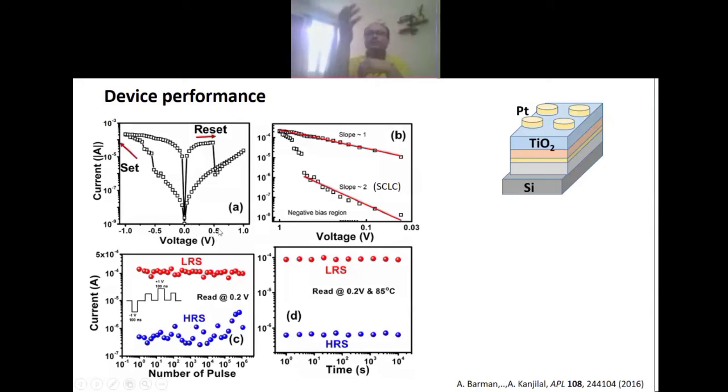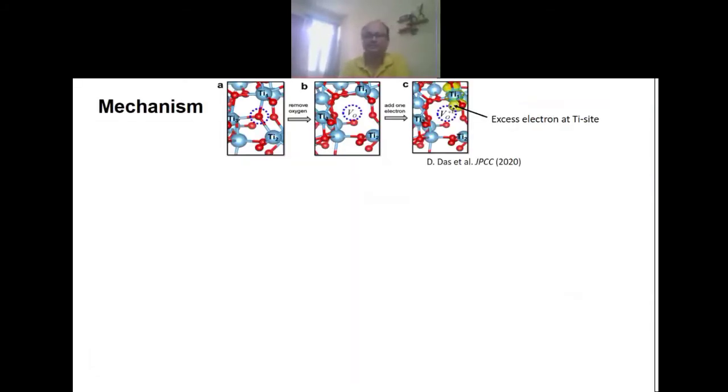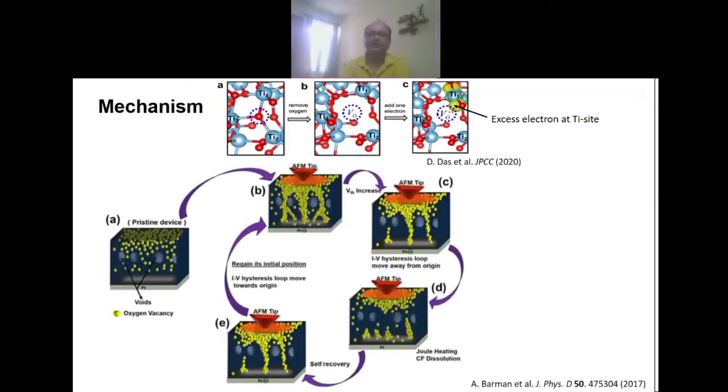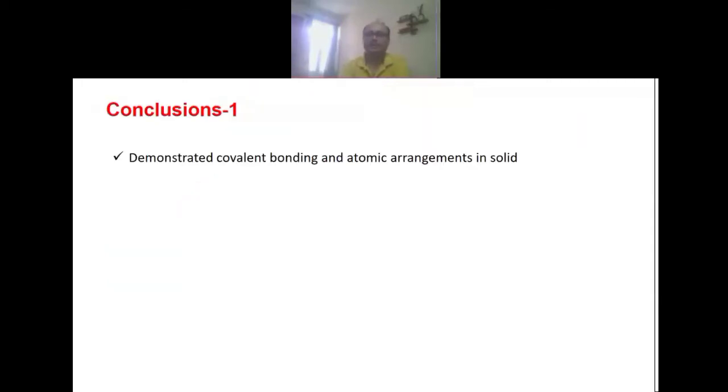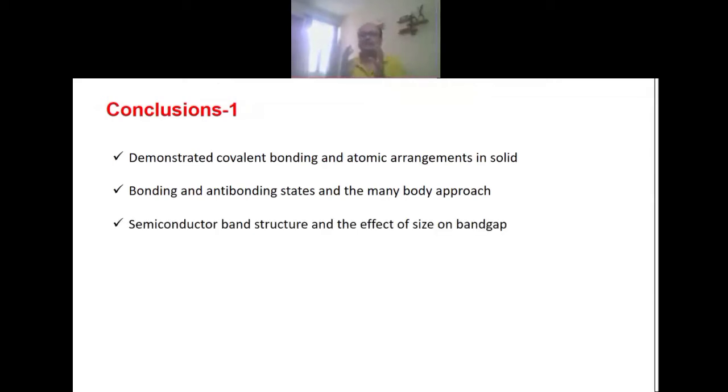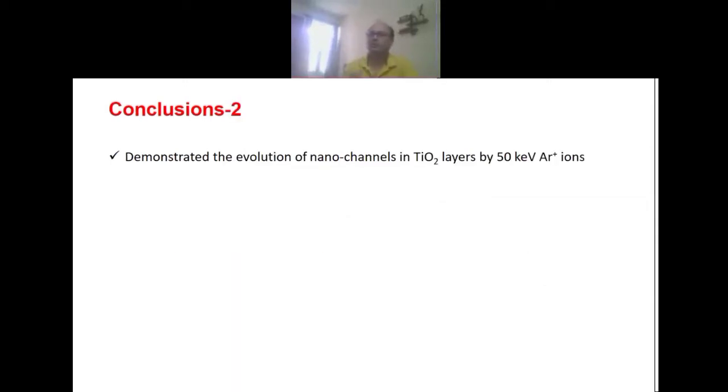That means that even silicon, the one I showed over here with an indirect band gap, by reducing the size can become a direct band gap semiconductor, and that's why it can also emit light in the visible range. Using that, LEDs have been prepared. There are lots of papers demonstrating that silicon nanocrystals can emit light in the visible range. So what we learned here is that by reducing the size, your band gap opens. But how? This is one part, and I'll come back to this point.